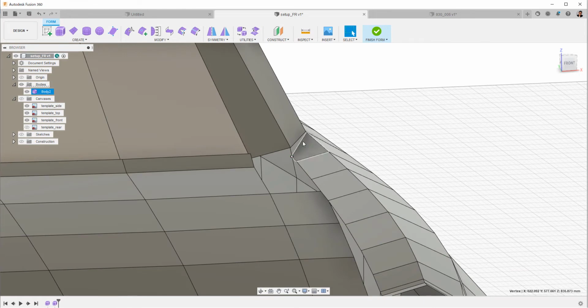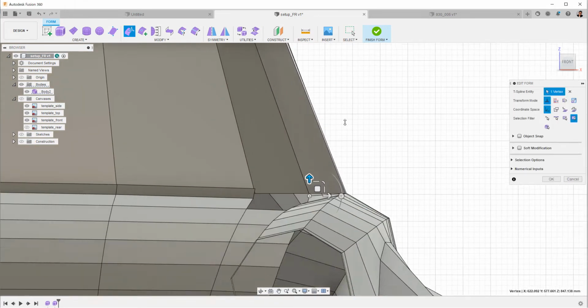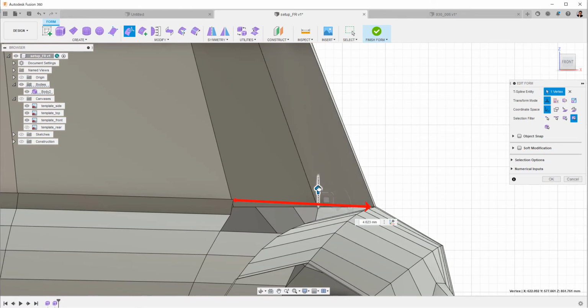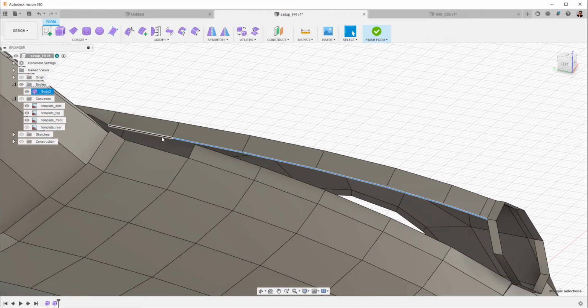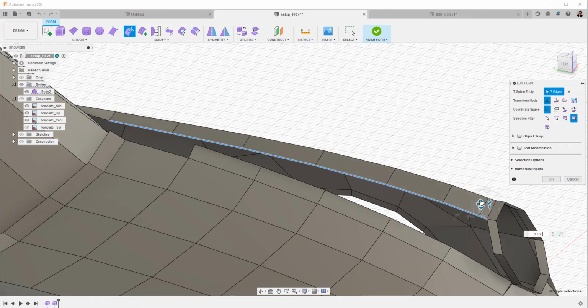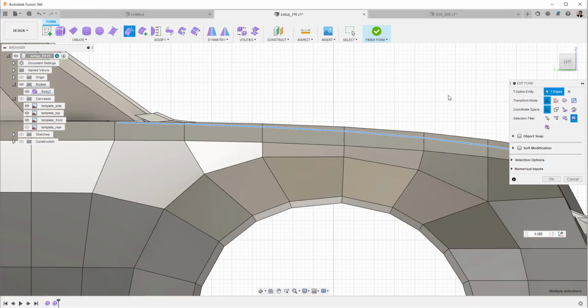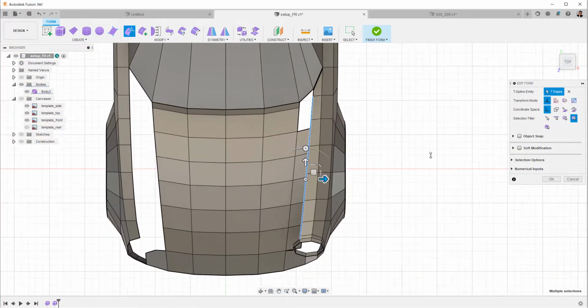Adjust the cowl detail of the hood. Adjust the front view so that the lines are connected. Select the edge between them. Snap the pivot to the front edge and adjust with the Z direction scale. Then select this edge. Hold down Alt and extrude to the middle side.